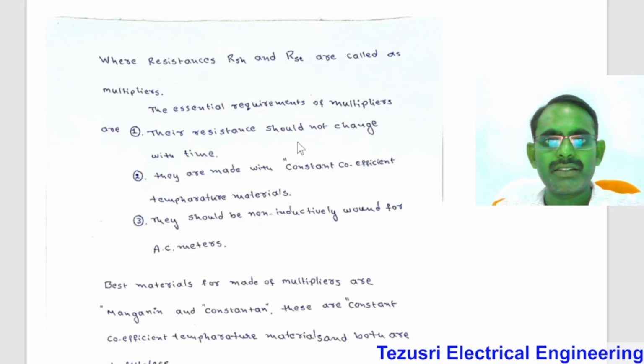The resistances should not change with time. The resistance of this RSH and RSE are not changing with time. They are made with constant temperature coefficient materials. They should be non-inductive wound for the AC meters.